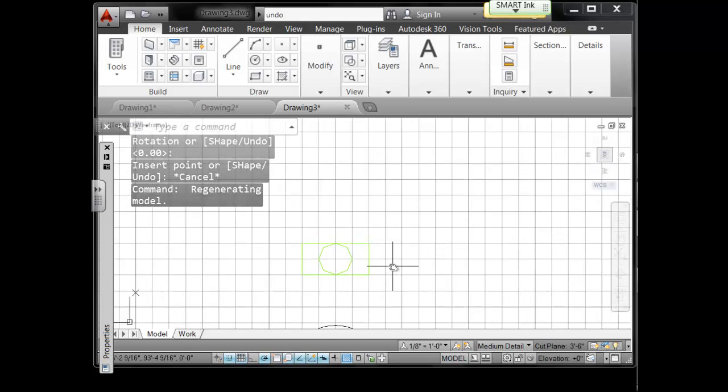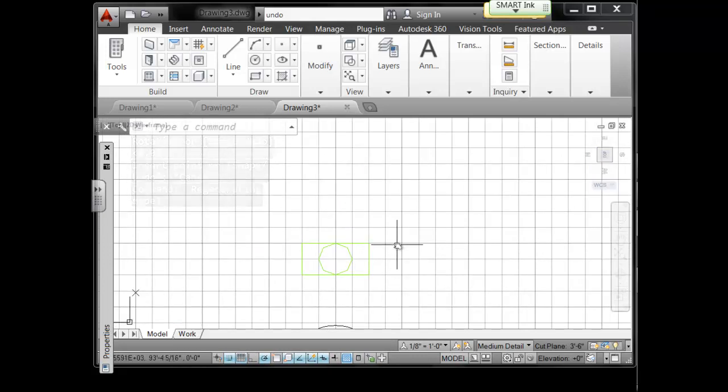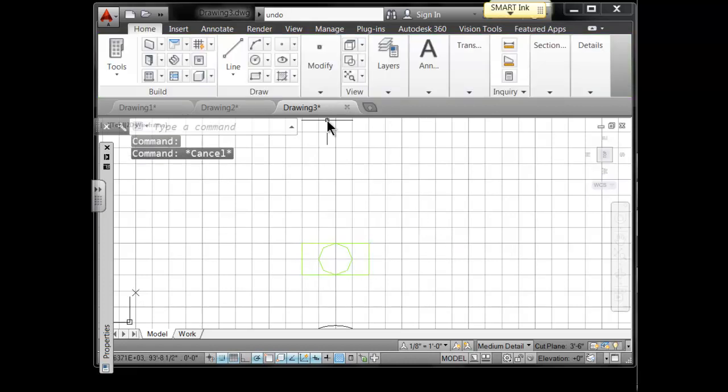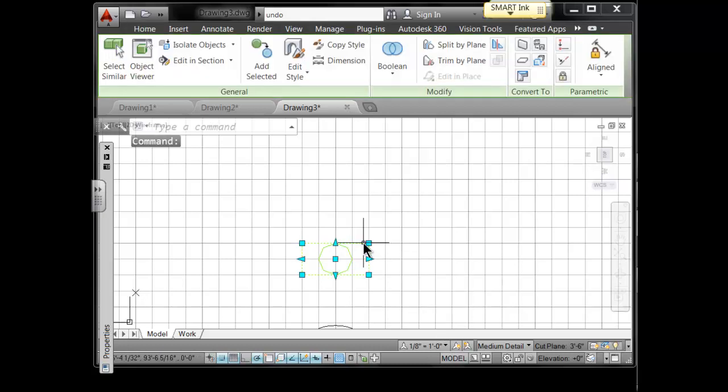And now we're going to do a Boolean operation. So you first touch the solid that you will be subtracting. And notice how the top command changed automatically. Check this out. Press escape and do it again. See how this ribbon tab is up here? The moment you touch the solid, look how it changes. All of a sudden it's all about your solid.